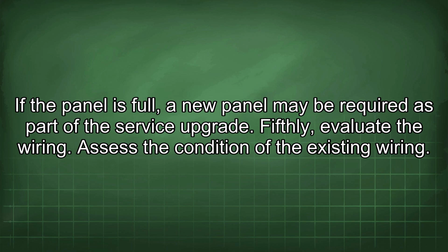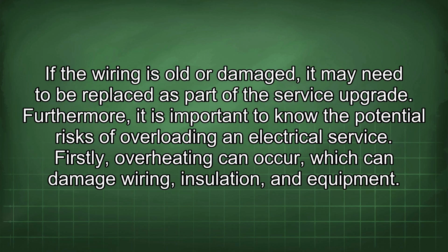Fifthly, evaluate the wiring. Assess the condition of the existing wiring. If the wiring is old or damaged, it may need to be replaced as part of the service upgrade.